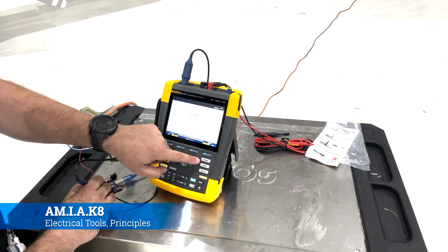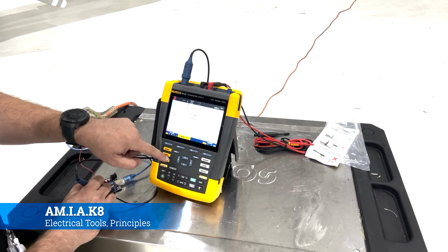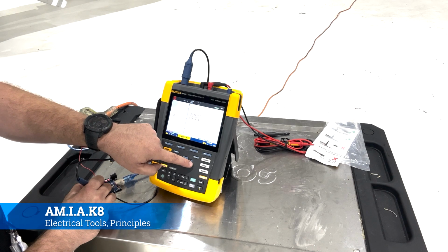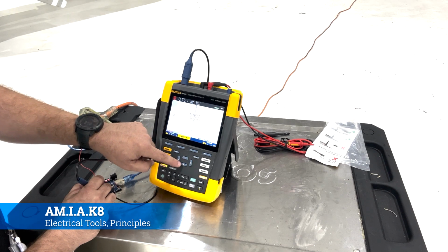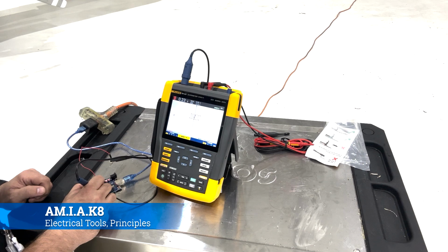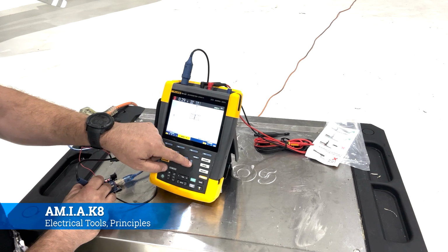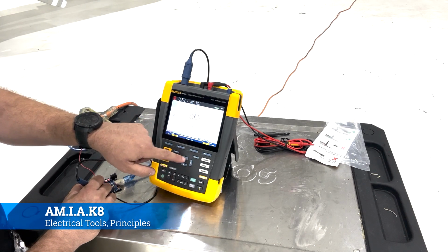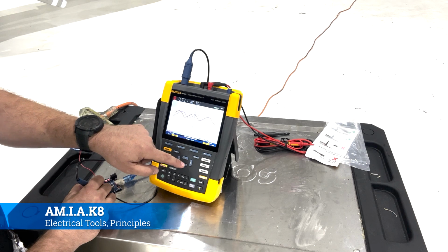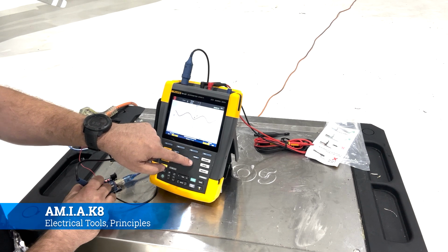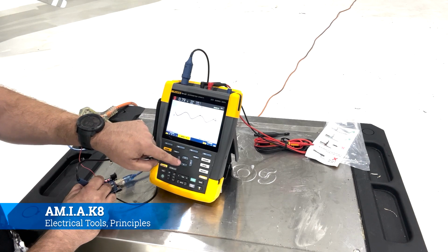We can use the O-scope to not only see how long the signal voltage is taking to go from bottom to top, but we can also see what range it's going to, from the very lowest to the very highest. If it's out of range, then we're not going to get the same type of movement on the aircraft that we would expect, and that could be part of our problem. Now we're going to deal with these a lot more in advanced avionics. This is just to give you some familiarity with what O-scopes do and what they look like.